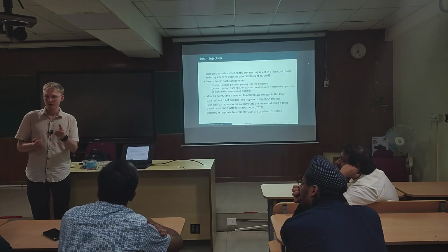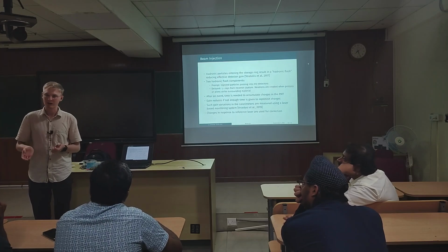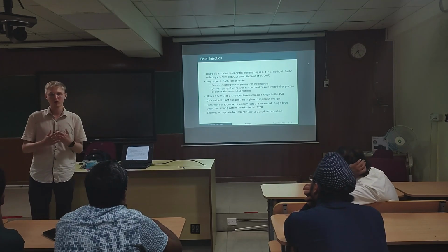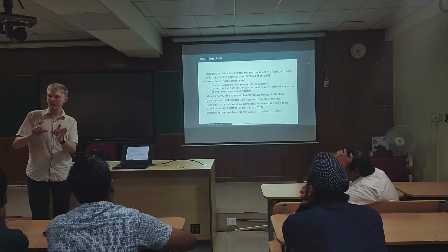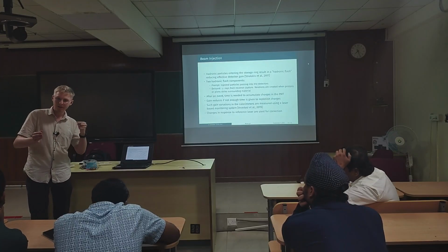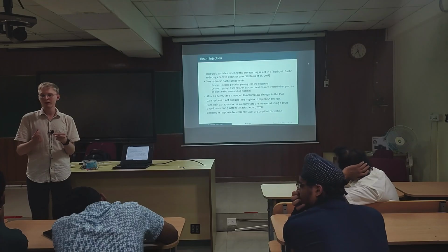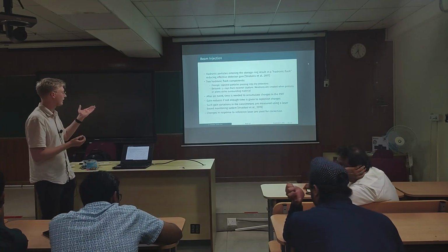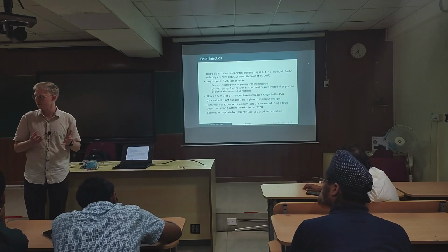So once you deplete all the charges, because you have a capacitance, it takes some time to get the charges back up. And if too many events are coming too close together, that means that one event depletes the charges, you record that event at a lower energy, but when the next event comes, maybe the charges have not been completely replenished, so you don't really get a true picture of what's going on.